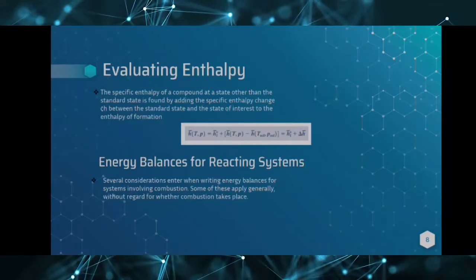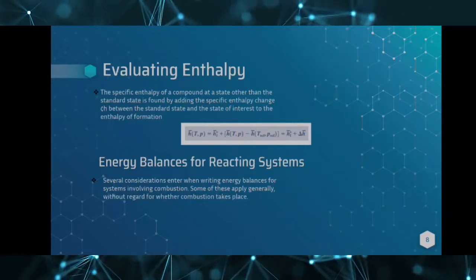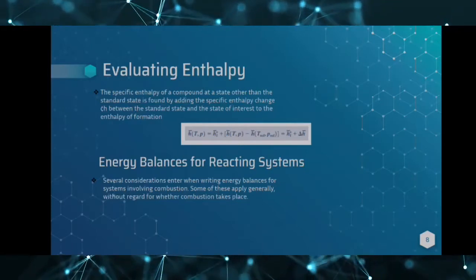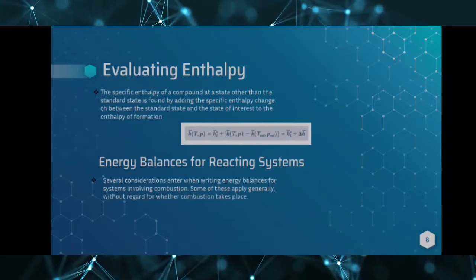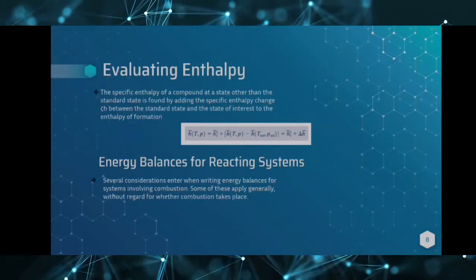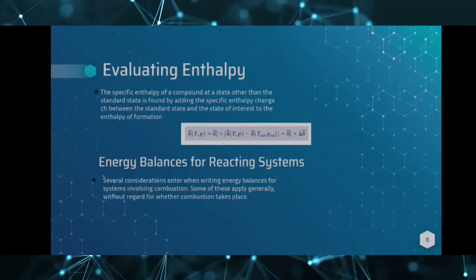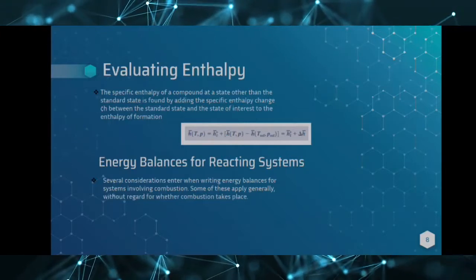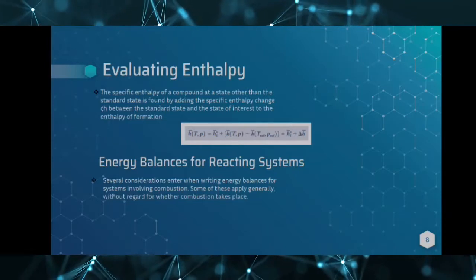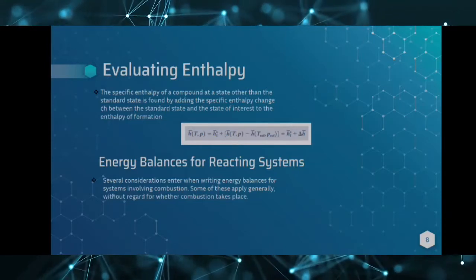Other considerations are related directly to the occurrence of combustion. The state of the combustion products also must be assessed. For instance, the presence of water should be noted, for some of the water present will condense if the products are cooled sufficiently. For cooling of combustion products at constant pressure, the dew point temperature method of example 13.2 is used to determine the temperature of the onset of condensation.